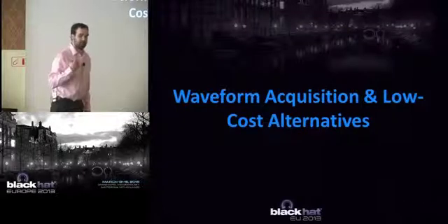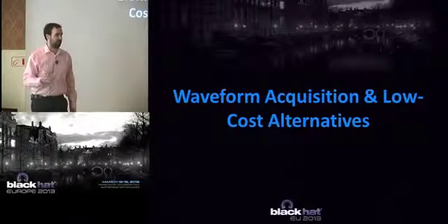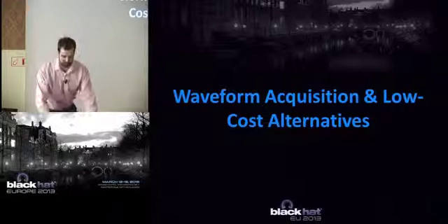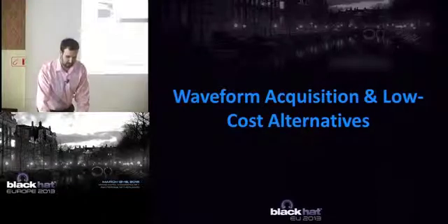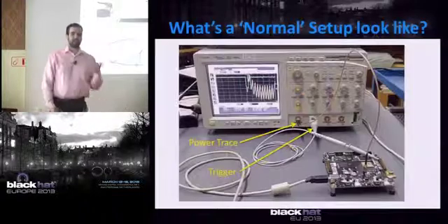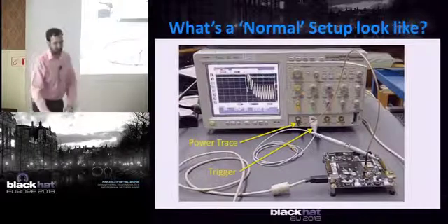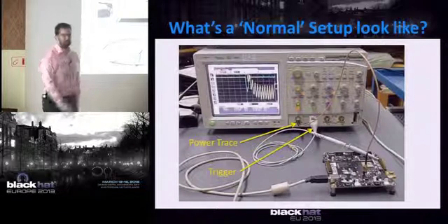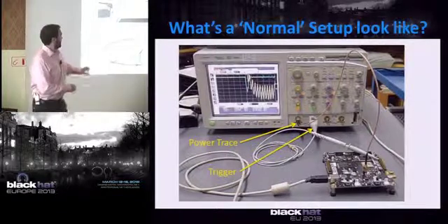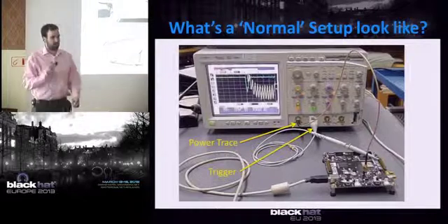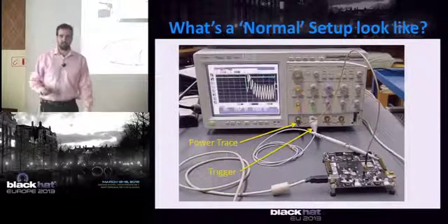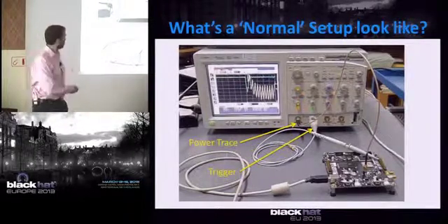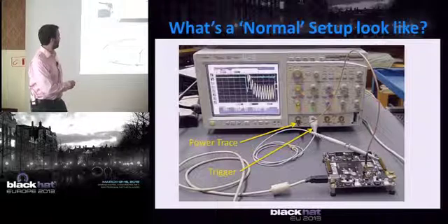So to do this, we obviously need to measure the power. We need to acquire those traces I talked about magically. Normally it might look something like this. This is using a hardware board called the Sasebo project, which is the standard evaluation board, and it's used in quite a few research papers. It has a resistive shunt, so you can measure the power across a resistor being used by the FPGA. And you just plug that into your scope.